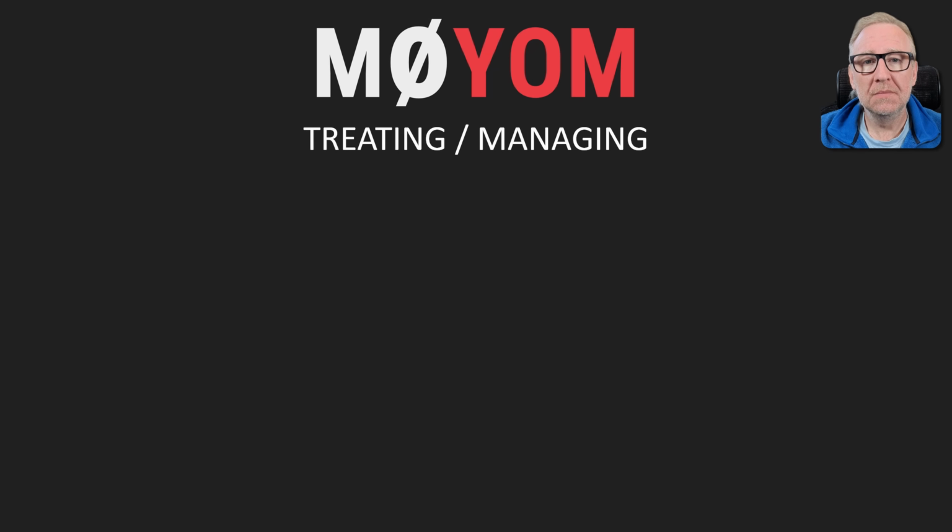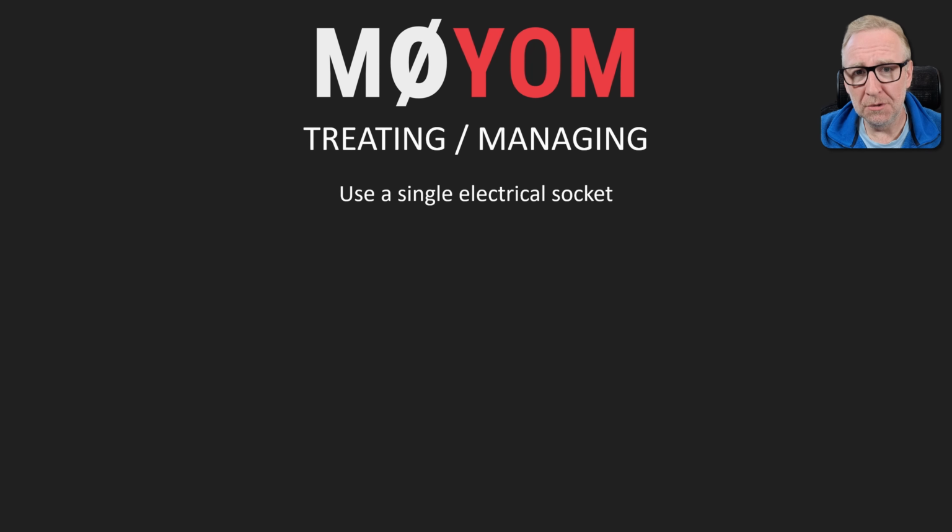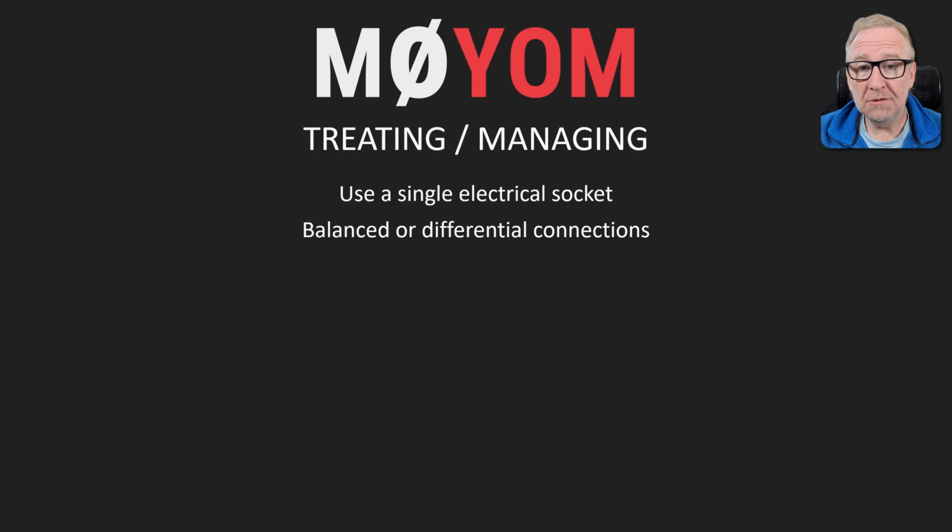So as I mentioned earlier, sometimes it's not possible to eliminate all the ground loops, but there are some things that you can do to reduce their effects. You can try to make sure that all mains powered devices are connected to a single electrical socket, typically through the use of a multi-gang socket adapter. This can sometimes help, especially with audio ground loops, but remember, you must take care to ensure you aren't overloading the socket. We can use balanced or differential connections between devices. These help to reject common mode noise that can be caused by ground loops.